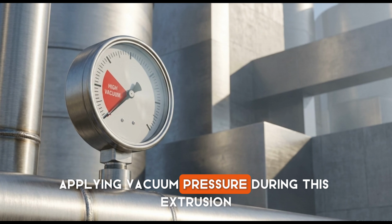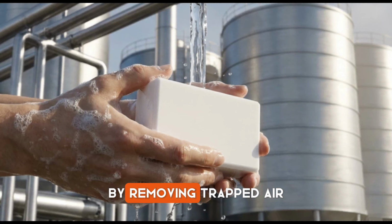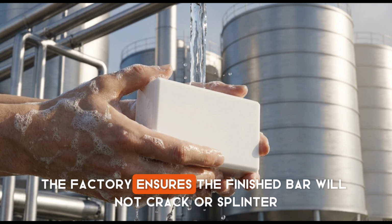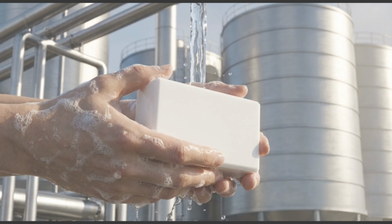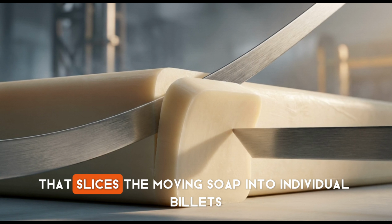Applying vacuum pressure during this extrusion ensures maximum internal density. By removing trapped air, the factory ensures the finished bar will not crack or splinter in a consumer's hands. The continuous log meets a high-speed wire cutting mechanism that slices the moving soap into individual billets.